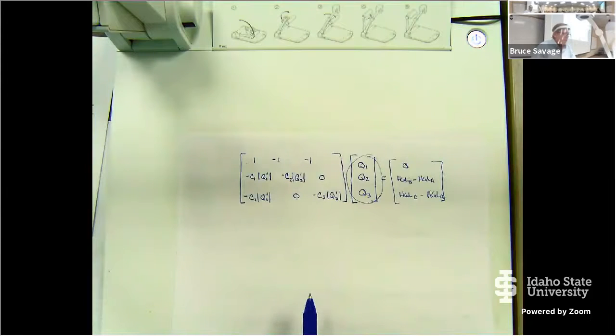All right. So I didn't get far enough to show you an example on the computer. So the homework then that was due today, we're going to make that due on Friday, and we're going to fix problem 2. So the hydraulic grade line at the junction is equal to 170, not the elevation. Okay. And then I'll also give you an elevation because I want you to finish the other problems where you figure out the pressure of the junction as well. But let the hydraulic grade line equal 170 and solve it, and I'll correct that and repost it. That will be due on Friday. If you've already uploaded it, that's fine. You should be able to reload it. Your latest version, not a problem.